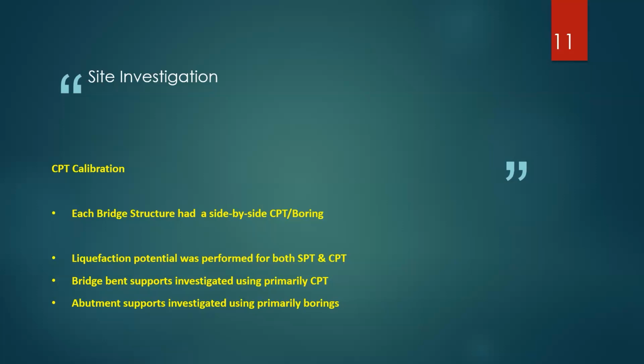And we did that. That was a mandate in the TP as well. We developed that collaboration with the Orange County Transportation Authority. So not only did we use that for investigation, but we also used it for investigating the liquefaction potential using both SPT and CPT. This was another calibration that basically calibrated the performance of CPT and its power in evaluating liquefaction directly, and compared that to the SPT evaluation of liquefaction and drew a comparison, which is, in my opinion, very valuable and priceless in the area of seismic design of bridges.